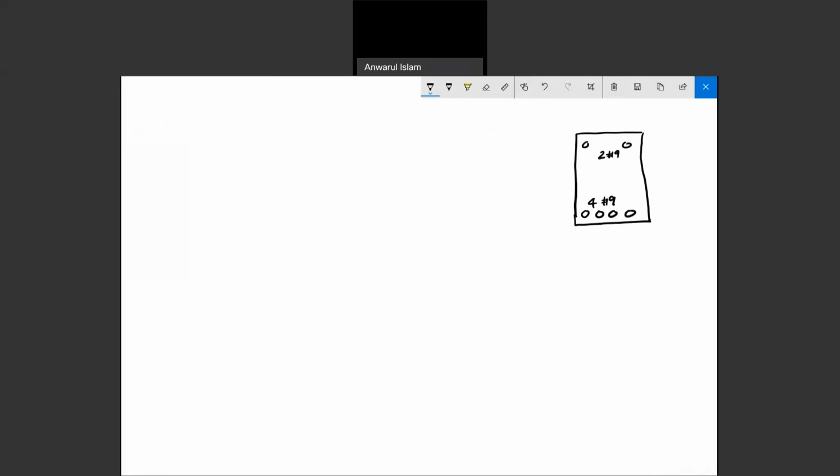The beam is assumed cracked, and since the beam is cracked, the neutral axis should be somewhere around the top of the beam. So let's say this is the location of the neutral axis, which is at a distance of y from the compression fiber. And our goal is to find the stress at the steel, which is right around here at the center of the steel, and that distance is given by these numbers: